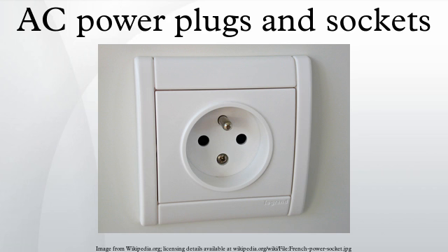This plug, commonly called a 13A plug, has 3 rectangular pins forming an isosceles triangle. As the BS 1363 socket is conventionally used with ring circuits, the plug has a fuse to protect the appliance flexible cable from overload.